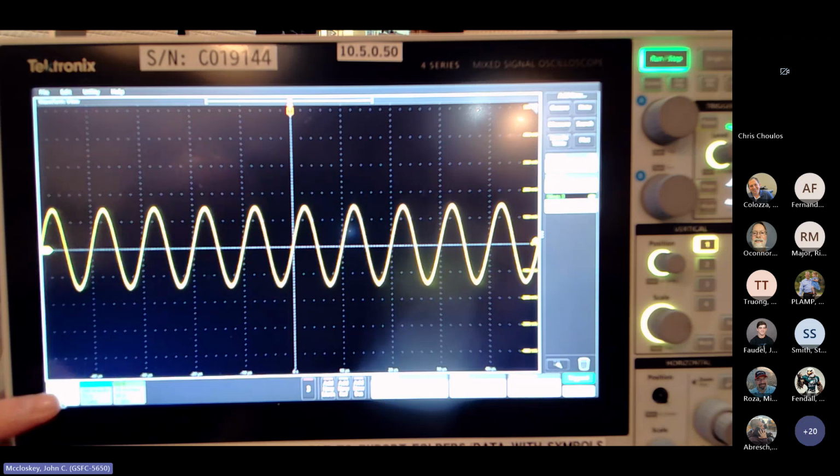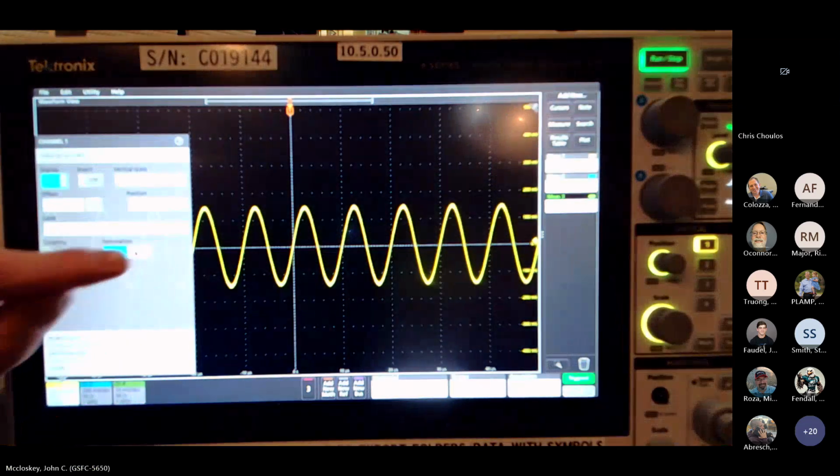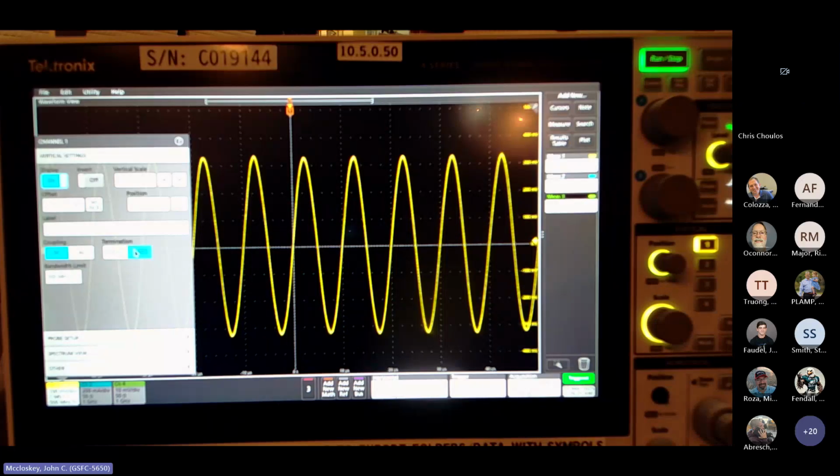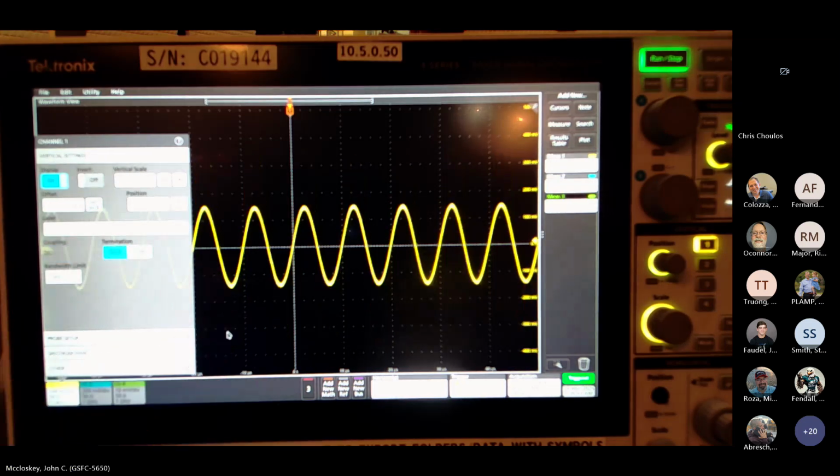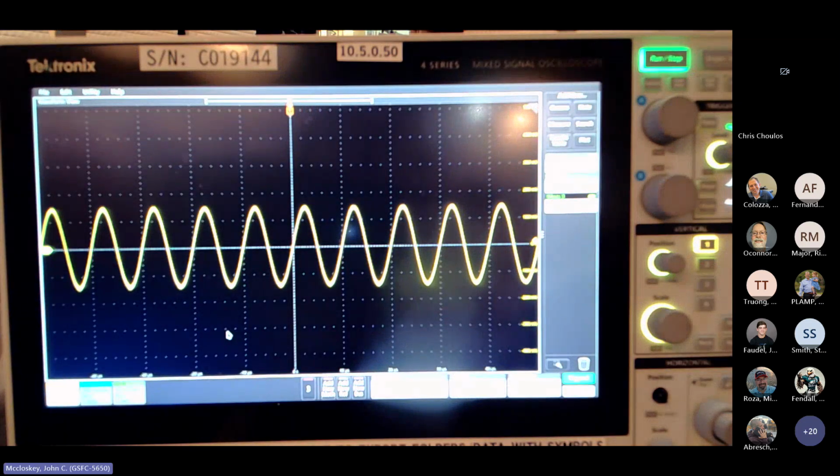And going to our 1 megohm input, it goes up to 230. So it's a little more than double now. When we're done here, I'll go back to the equivalent circuit and we'll talk about why that is. Okay. But it's a little more than double. You're getting up to the edge of the lossy part of the curve for the probe itself. Okay. So now we go to 300 kilohertz.